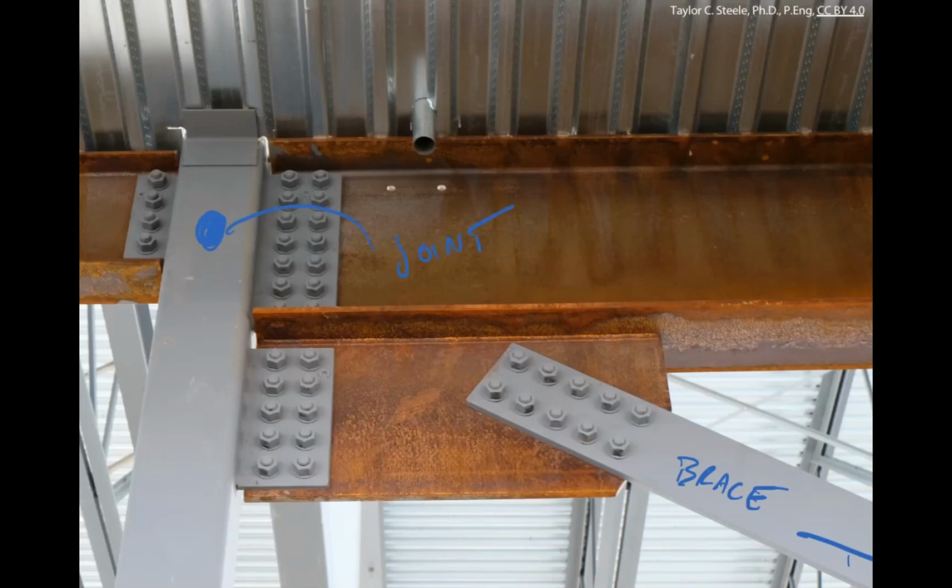We can see that it's not really an infinitely small joint. It's not a particle. It's a finite rigid body, but we're more or less going to assume that all the forces that come through these members pass through that single point. And so the tension in the brace is going to work through that point. The potential for compression in the beam above is also going to work through that joint, and the potential for compression in this column is going to work through that joint.